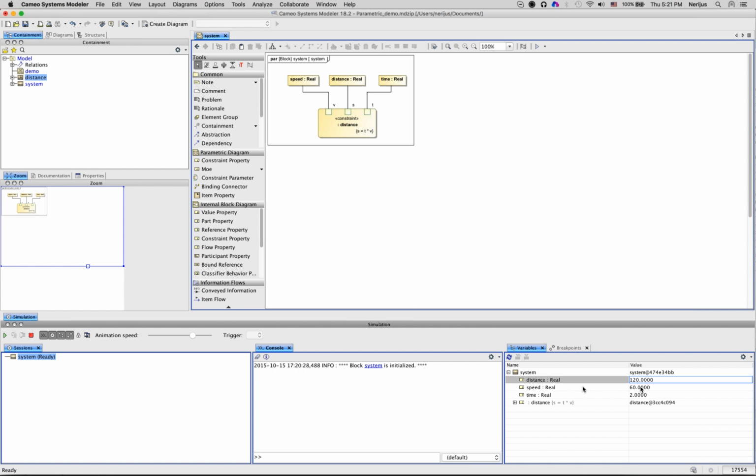That's very, very useful if you have dozens of those models and you don't know who changes the value. So you can plug in a user interface mockup, so the user can interact with the model and change values. You can change values here directly, or some external source can change the values using our API, and so on and so forth. Every value change automatically triggers pending values update. So here in the middle you see the console and the log, and we have different categories. If you want to debug, switch to debug mode, and if you press refresh, you can force recalculation of all constraint blocks.